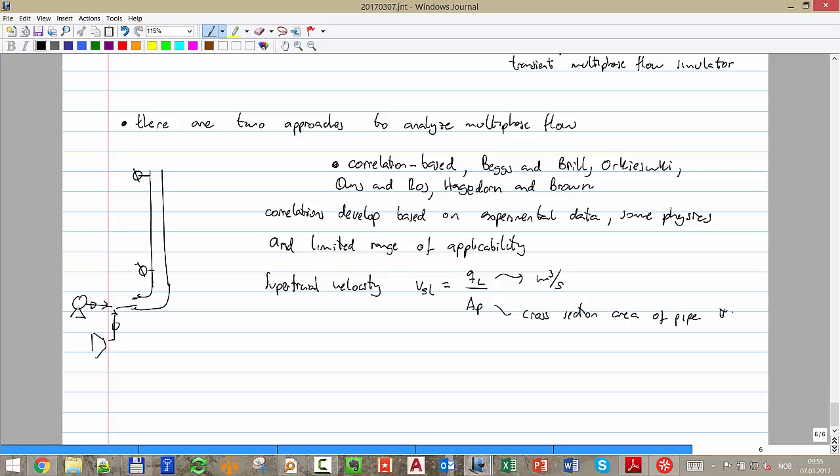Okay, that is just pi r squared. And the superficial velocity of the gas is the Q of the gas divided by the total area. So if they make a plot of USL versus UG, or USG versus USL, they could identify that some particular combinations gave you bubble flow.